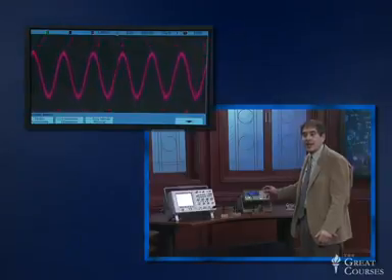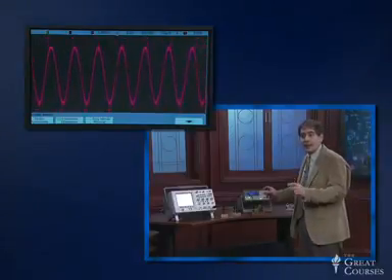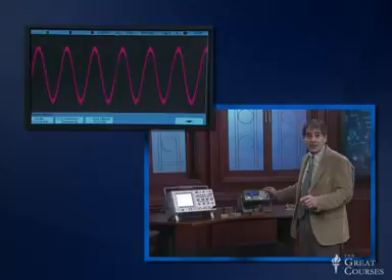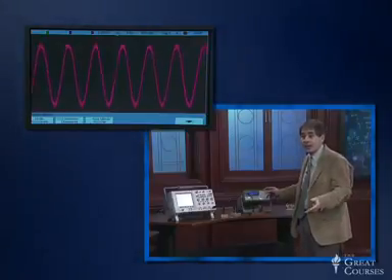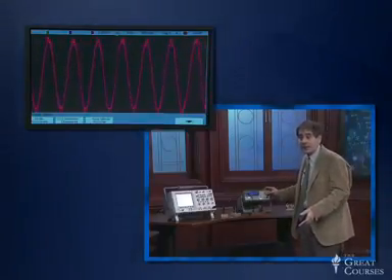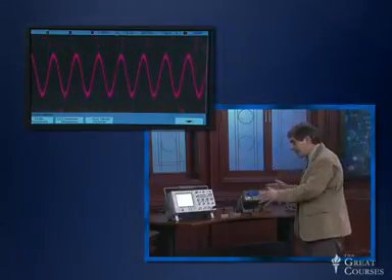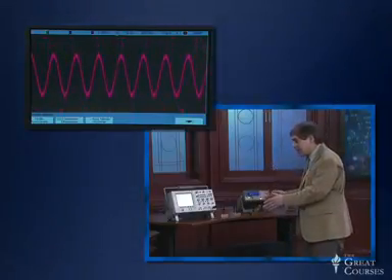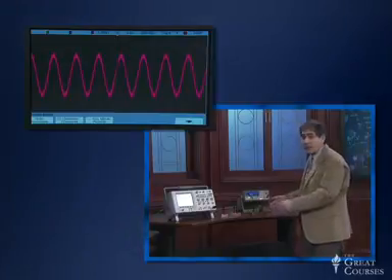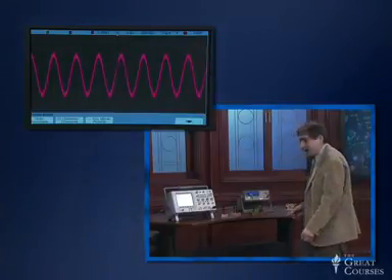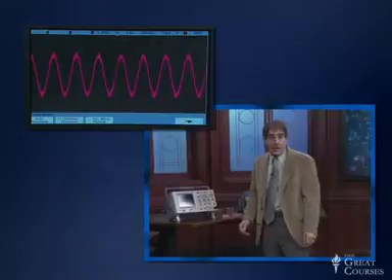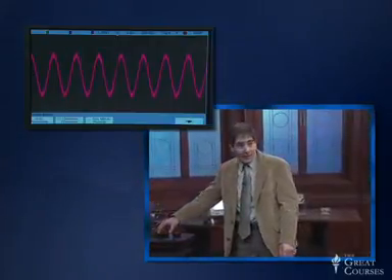We see the current, which I'm measuring by measuring the voltage across the resistor, because current and voltage in a resistor are in phase and are proportional. So there is the resonance peak occurring in that circuit. This is a resonant circuit. This particular circuit resonates at that frequency of about 1440 kilohertz. That's the natural frequency it would like to oscillate at. So that's a resonance effect.